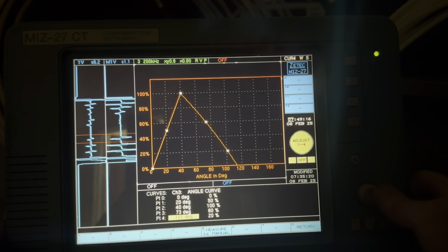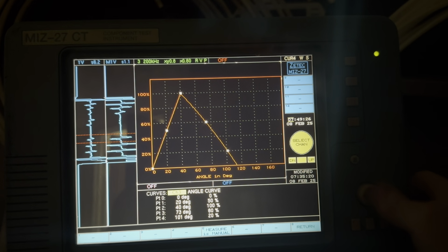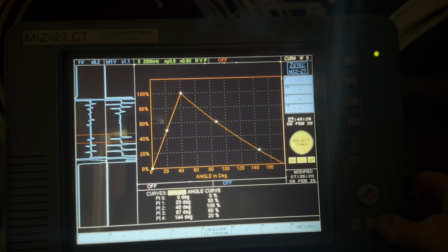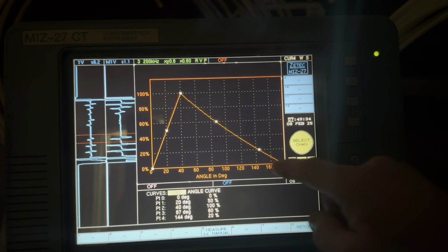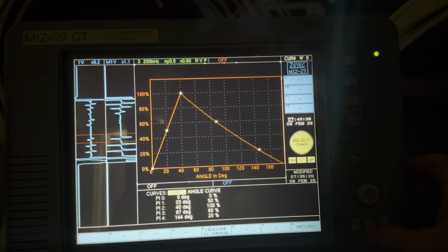Again, use the as-built dimensions. If that was 22%, we'd dial in 22. But for this, we'll keep it 116, 20. So now let's go into the curves, and then we'll go back to channel 1. Most phase spread works really good for sizing OD flaws because there's a lot of different phase angles to choose from, and each phase angle has a different depth.